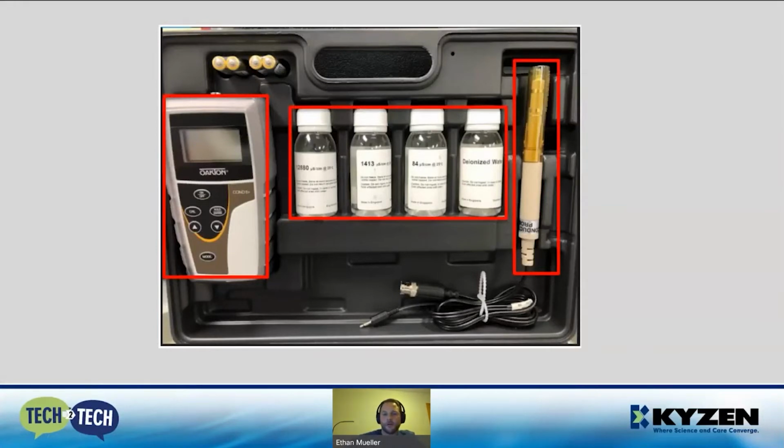Once we've allowed the sample to cool down to ambient temperature, the first thing we're going to want to do is plug our probe into the meter and, of course, turn the meter on. Then we're going to want to submerge the probe. Both of these metal bands here, we want to submerge into the wash solution, and our meter will generate a reading for us. And it looks like we're at 10 millisiemens.